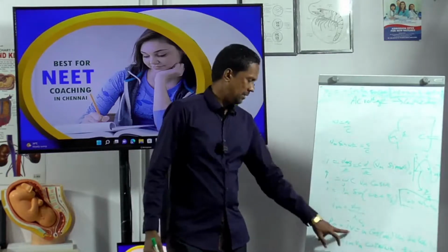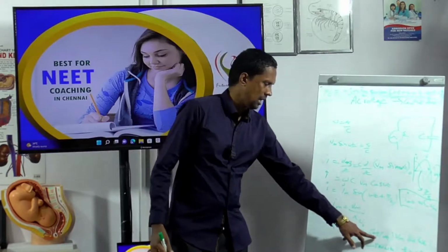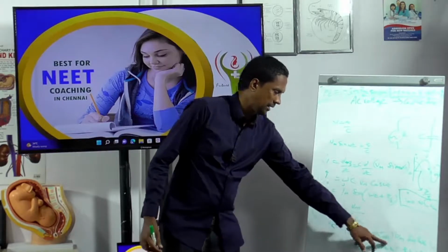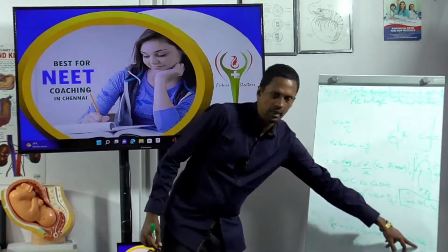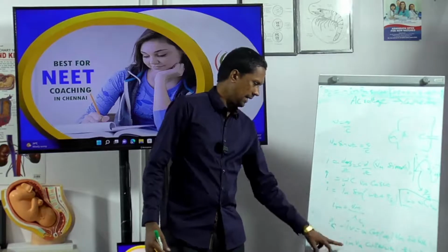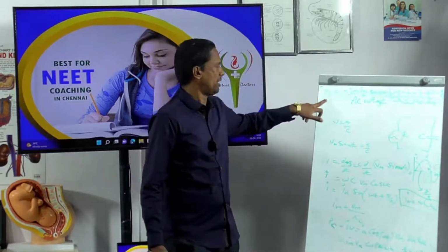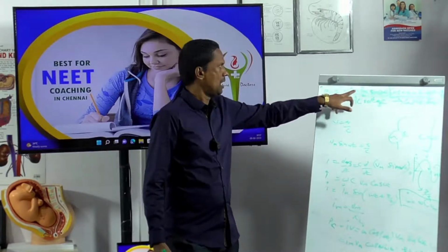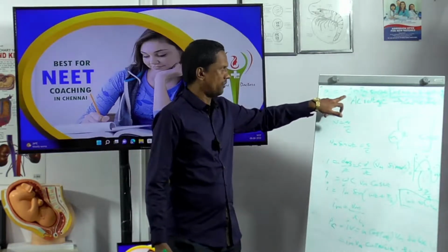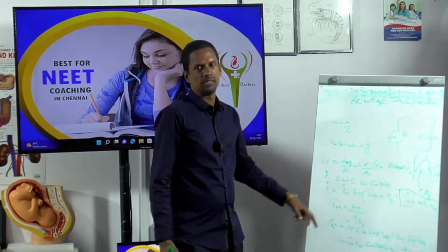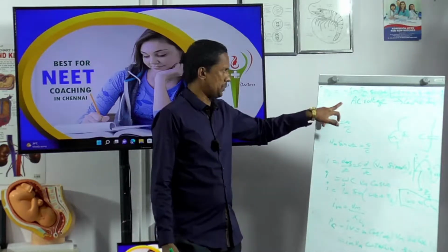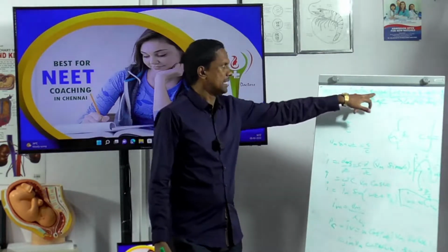So PC is equal to I into V. I is equal to Im cos omega t, and V is equal to Vm sin omega t. If I multiply both, what will we get? Im Vm cos omega t sin omega t. Finally you will get PC is equal to minus 1 by 2 into Im Vm sin 2 omega t.